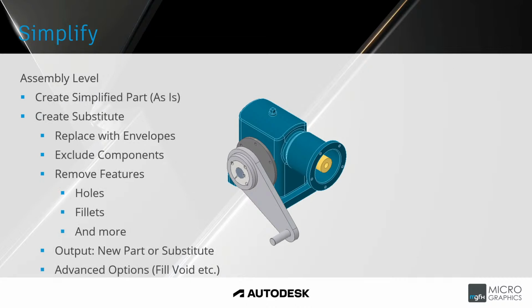Then moving on, still within the Simplify arena, we have the option to create a simplified part. So what this will do is we'll take the assembly as is. So whether you have a state active in the assembly that reduces the quality of the geometry, or whether you have a view representation active that removes components, you can create a simplified part of the assembly as it is. And essentially this extracts all of the assembly information and creates a single part file to represent that assembly geometry.